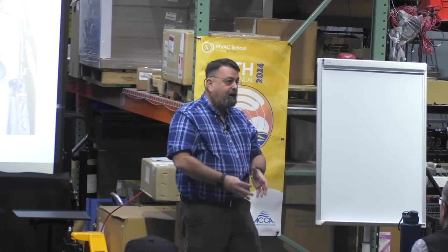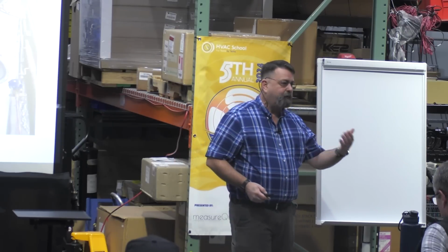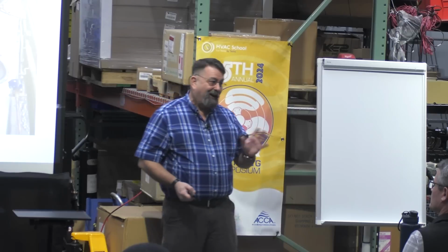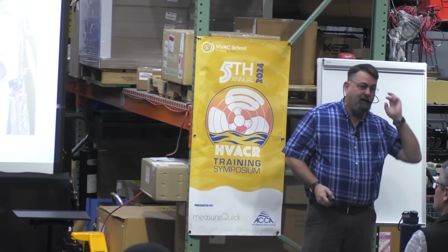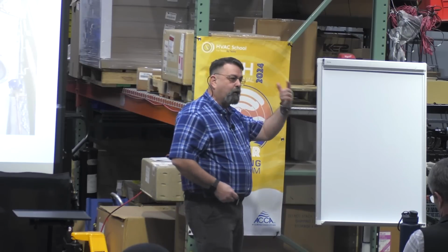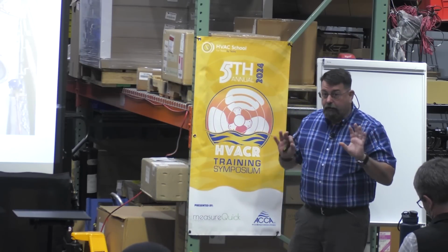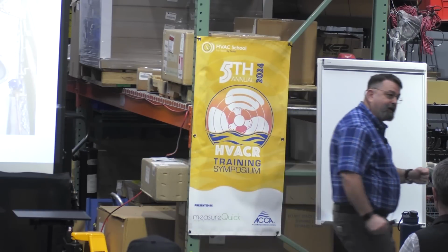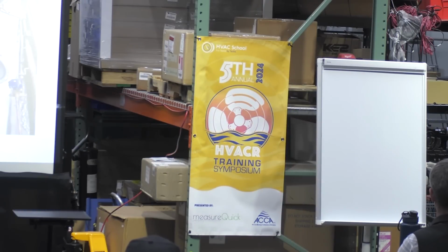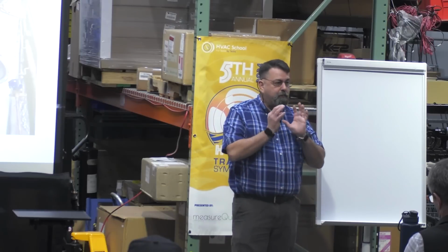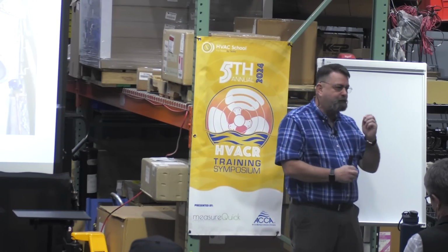So I do that by creating, somewhere in the neighborhood around 300 CFM, my airflow velocity that's coming down. Okay, that's creating that little wall. It might be, in high efficiency cases, I've seen as low as 150. Right, these are really weak air curtains. If we smoke one of these cases and we can watch that air flow through there, it's kind of cool. On those 150s, the more modern cases, when a customer walks by with a shopping cart and she's walking quick, that smoke follows her, right? It's not strong enough to prevent that, right? Because we're saving power by trying to make it just as small as possible, just barely strong enough.